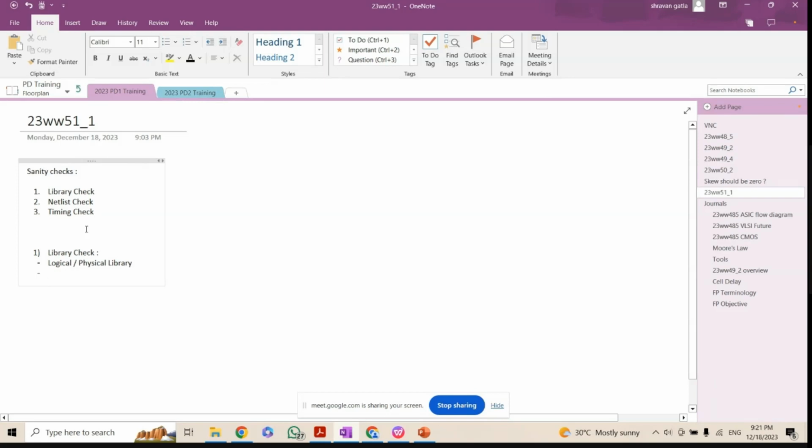So in this design, let's say these are the two flops I drew here. This has some logic. If it is not clocked, then how do you check this capture clock path, clock delay? You don't know, right? So your timing will not be accurate. You will see some random timing, and it won't meet timing. So that's why, the moment you get the inputs, you need to check the health of the SDC. If you have unconstrained endpoints, then it leads to wrong timing.